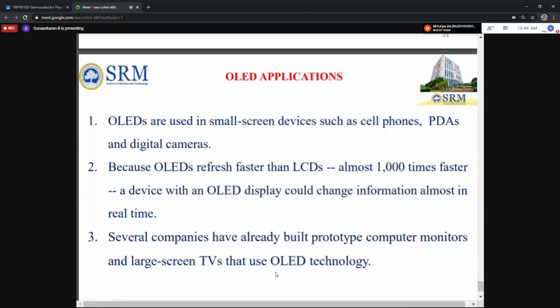I think first you see what is the structure of OLED, how many layers are there. Then you go through each and every layer and see what is the role of each layer: substrate and seal, and the cathode and anode, that is the input, the negative and positive layers. Then the organic layers. Then how the light is emitted. That is the working concept of OLEDs, and what are the different types of OLEDs available in the market. Then what are the advantages, disadvantages, and applications.